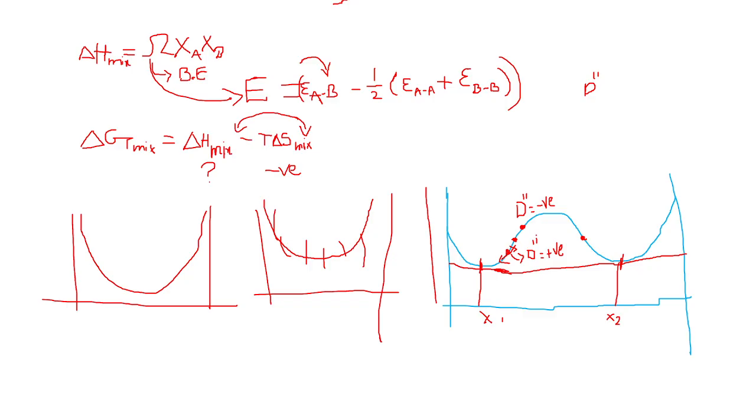Now, that means the free energy change is negative. That means if you are at this composition, because of the large free energy change, we do not even need a nucleation. We do not even need nucleation and growth. It just happens, like the movement of atoms, the migration of atoms across the boundary. That's all.